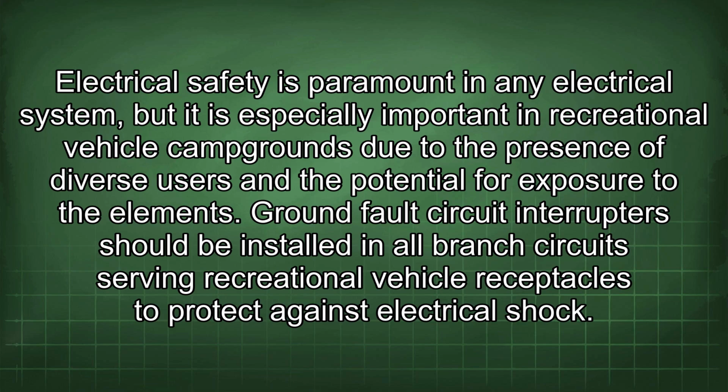Electrical safety is paramount in any electrical system, but it is especially important in recreational vehicle campgrounds due to the presence of diverse users and the potential for exposure to the elements. Ground fault circuit interrupters should be installed in all branch circuits serving recreational vehicle receptacles to protect against electrical shock.